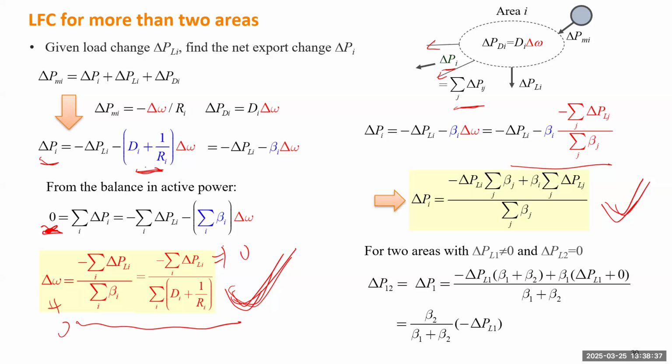And also we know we cannot make R too small because that can cause some stability issues. It only can reduce the steady state frequency deviation, but it doesn't guarantee your entire closed loop control system to be stable, right? Based on what we have tried, based on the Routh method and Routh table, we know there's some stability limit. So then we need to talk about the limitations of a governor control system.